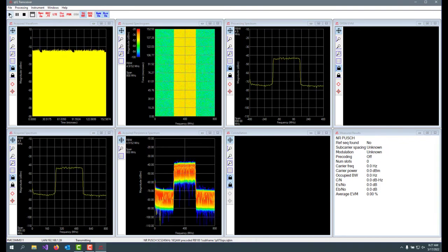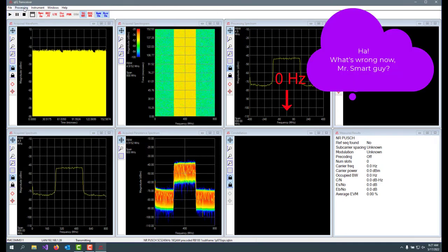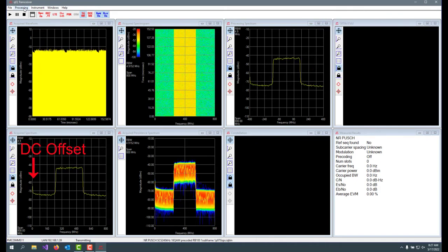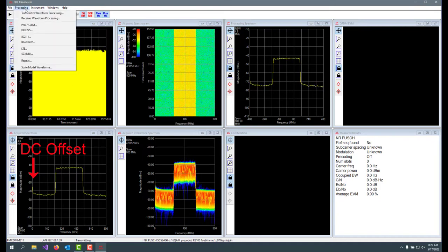After starting again, we see that the processed data is now at baseband. However, the DMOD is still not locking. The problem is the DC offset of the ADC. This small signal is keeping the correlation with the reference sequence from succeeding.